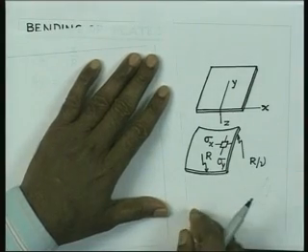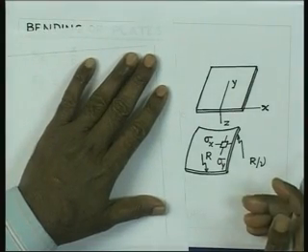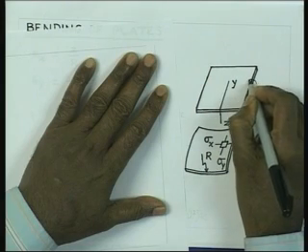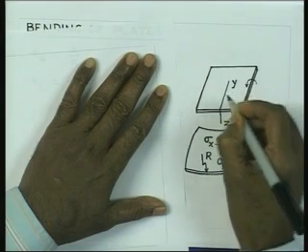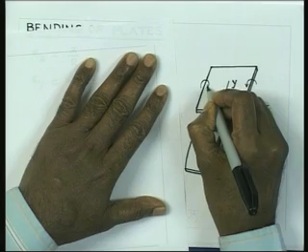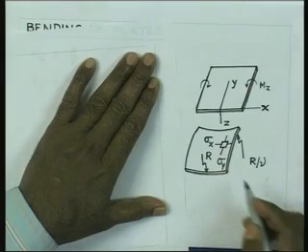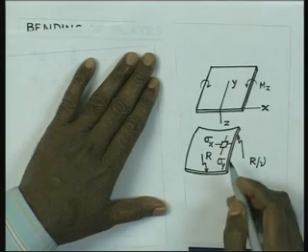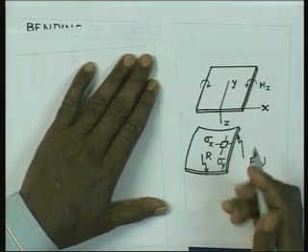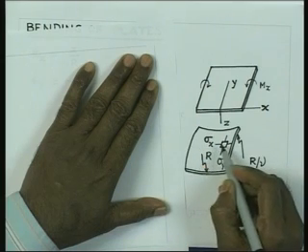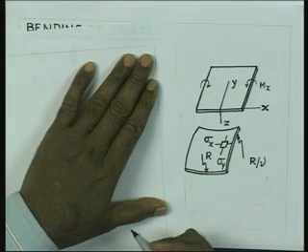When you try to apply bending load to such a plate, let us say we apply the bending load in the xz plane like this, and we would like to indicate this moment by Mx. So, when you do that, what you find is that we are trying to have bending generated like this, the surface should have curvature like that,